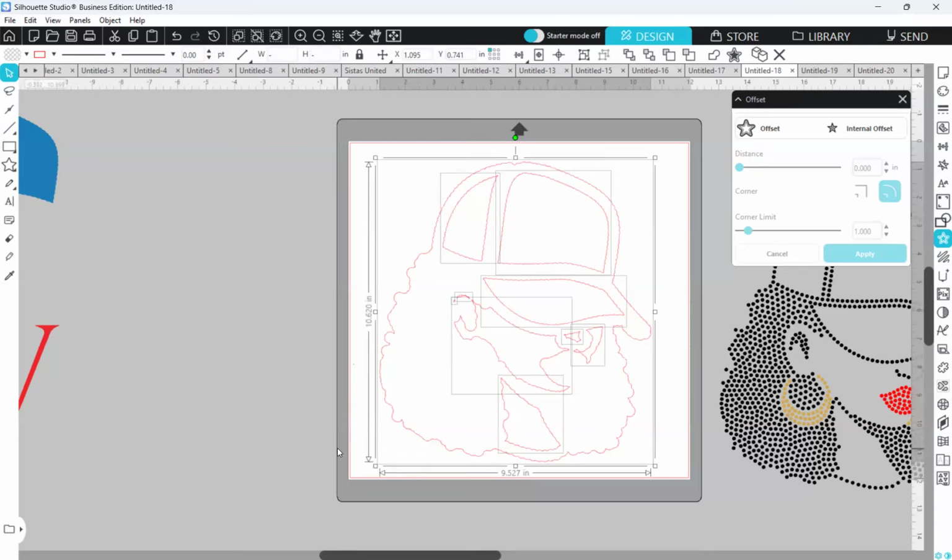Where do we find the release compound path? When you right click when you have it selected. So make sure you have a box around the entire offset. You right click with your mouse and you should see release compound path. Okay, and then we click that. Yes. Okay, I have that.